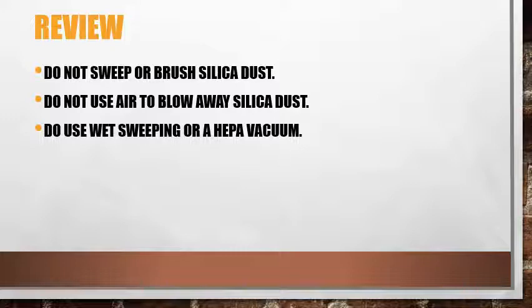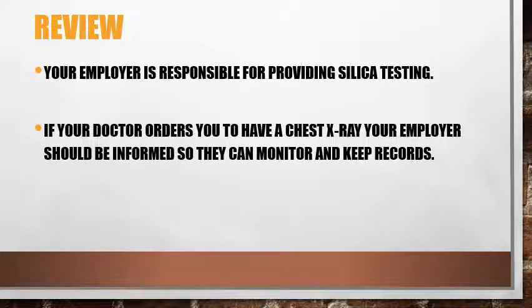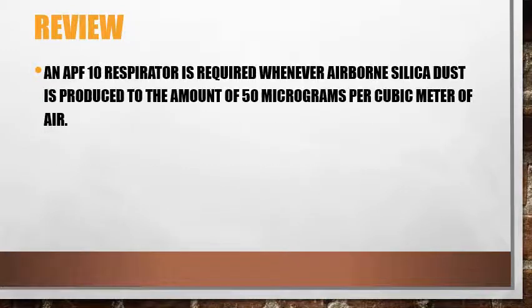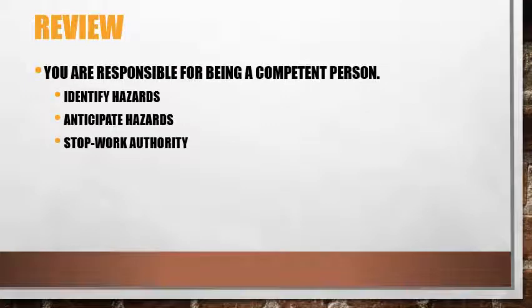Do not use air to blow away silica dust. Use wet sweeping or a HEPA vacuum to clean up silica dust. Your employer is responsible for silica testing and treatment. If your doctor orders you to have a chest x-ray, your employer should be informed so they can monitor and keep records. A respirator with at least an APF 10 is required whenever airborne silica dust is produced to the amount of 50 micrograms per cubic meter of air.